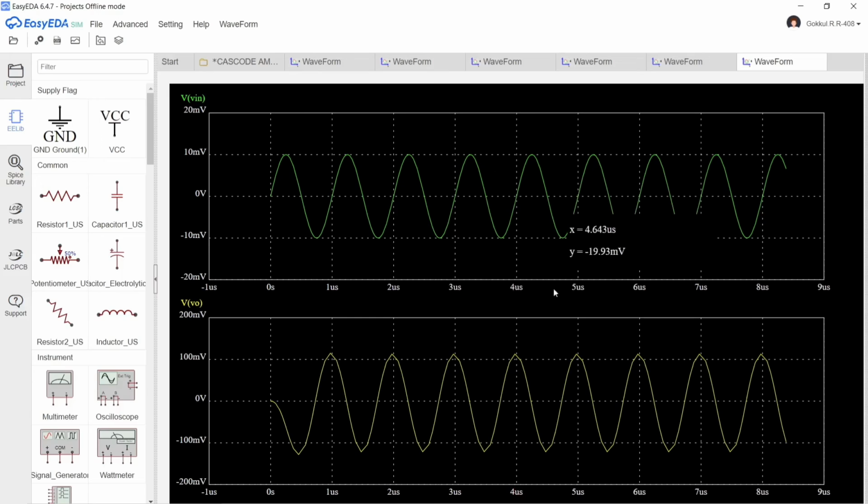So here we have the graph. And here we have the peak value as 116.637 millivolt. And similarly here we have minus 118.739 millivolt. Now the voltage value is getting decreased. So the value increased from 100 Hz to 400 Hz and became constant from 400 Hz to 100 kHz and started decreasing from 1 MHz. So we will see the frequency response graph in AC analysis.